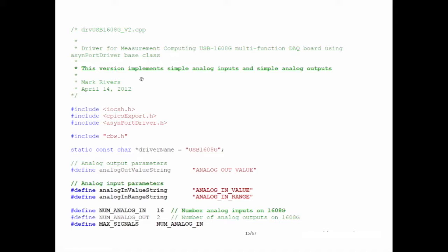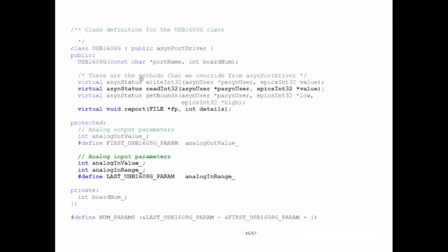And again, you can see that we're defining a bunch of parameters. So we're having 16 different parameter tables, one for each address. It's a little bit wasteful because there's only 2 analog outputs, so there are parameters for those in the remaining 14 tables that are not needed. It's not very efficient, but we're talking about a small amount of memory, a few hundred bytes.